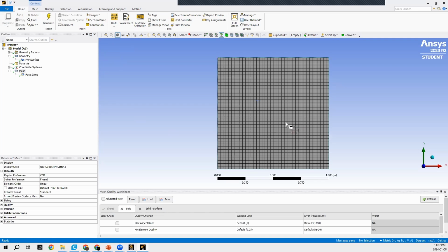And we can see that the mesh is a lot more refined than it was. It's still pretty coarse, but it will be able to capture the finer details for the little secondary vortices that are going to occur in the corners of our cavity. So next up, we're going to create some name selections in order to specify different aspects of this geometry. And this will be easier later on in Fluent in order to initialize and implement our boundary conditions.